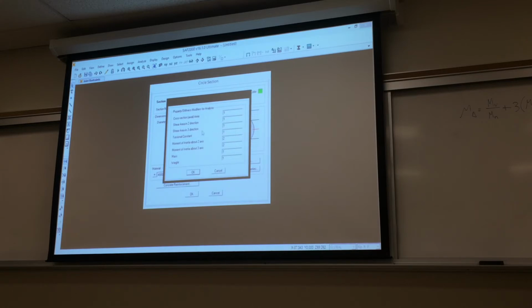So this is why sometimes normalizing can be really helpful. It lets you, let's say, generate lots of different cross sections, but instead of having to give each one its own individual properties, if they're relatively generic, you can just come in here and use set modifiers to quickly change different parameters and have, let's say, just kind of a default section, and then you modify that section for other applications.